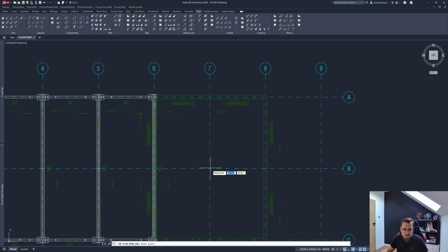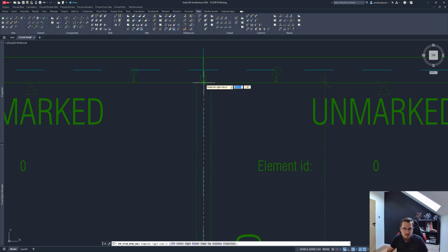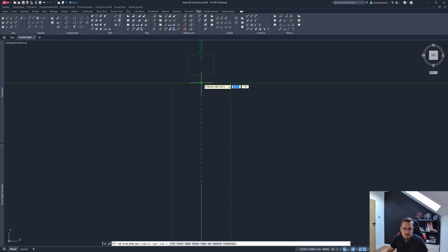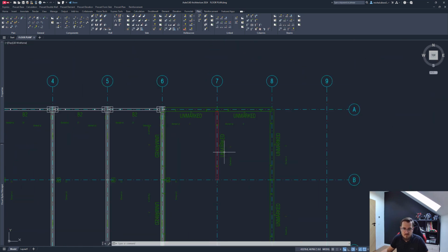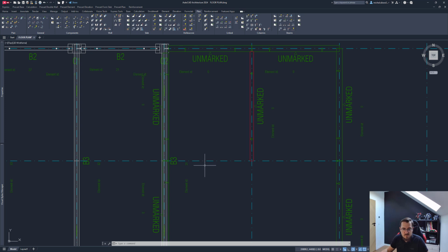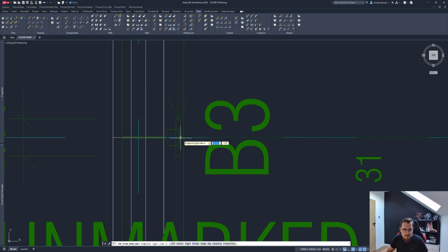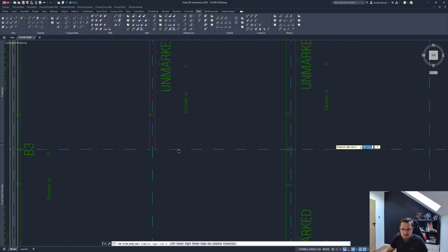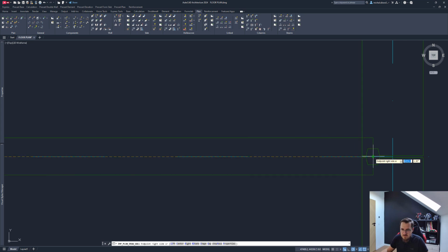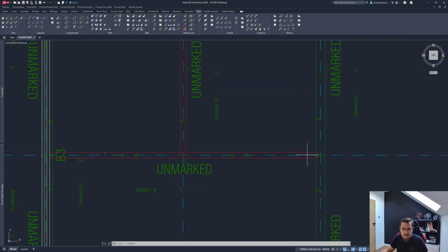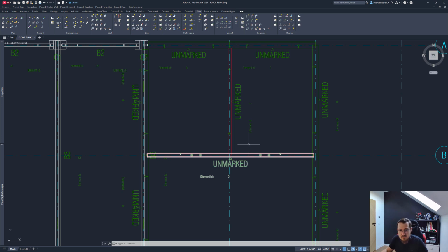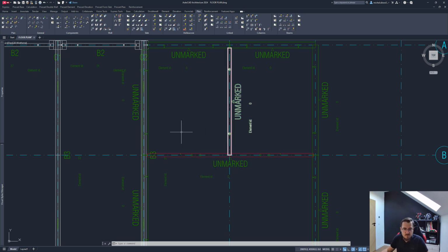I'm going to first start our wall from here, right? And end it here in the middle. As you can see, the wall is in red. It's too big. Right. Let's create another wall here. I'm going to do that here, on the axis, doesn't matter. It really doesn't matter that I'm not perfectly aligned. We'll fix that later, right? So that's going to be super easy for us.